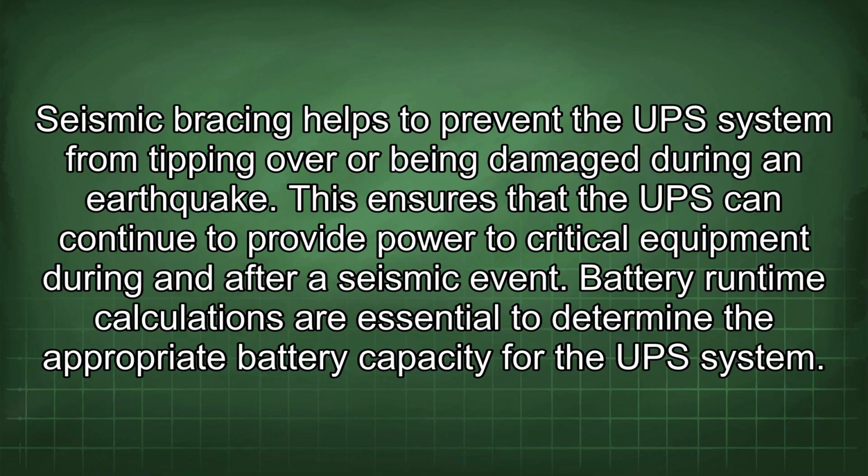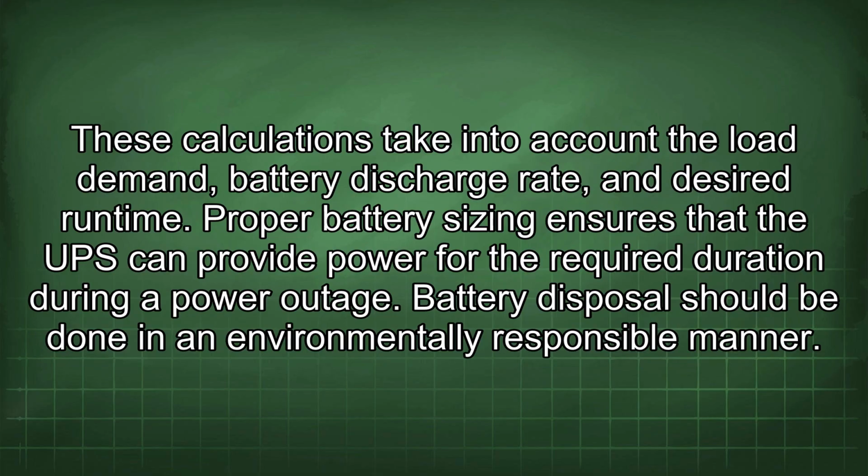Battery runtime calculations are essential to determine the appropriate battery capacity for the UPS system. These calculations take into account the load demand, battery discharge rate, and desired runtime. Proper battery sizing ensures that the UPS can provide power for the required duration during a power outage.